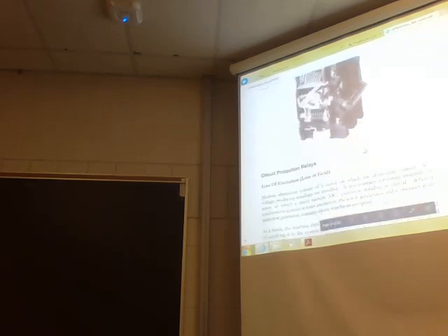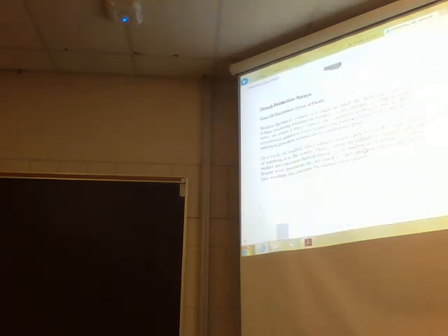Circuit protection relays. Modern alternators consist of a stator on which the alternating current voltage producing windings are installed. It also contains a rotating armature or rotor on which a DC excitation winding is placed. When a synchronous generator loses excitation, the rotor accelerates and operates as an induction generator running above synchronous speed.